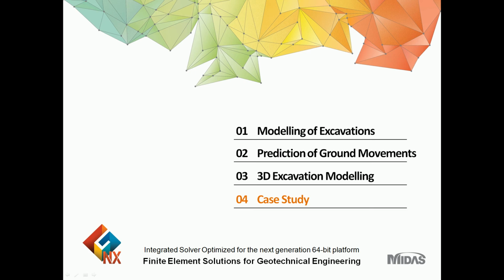The object of the study has been to investigate the analysis of retaining walls using the limit equilibrium approach as well as 2D and 3D FE models, and compare the results with some field data to conclude on the advantages and disadvantages of all three approaches. The study obviously has a wider application to a variety of civil engineering and infrastructure projects, such as construction of deep basement excavations, buried structures and services, and the effect of such excavations on the surrounding areas and adjacent structures.